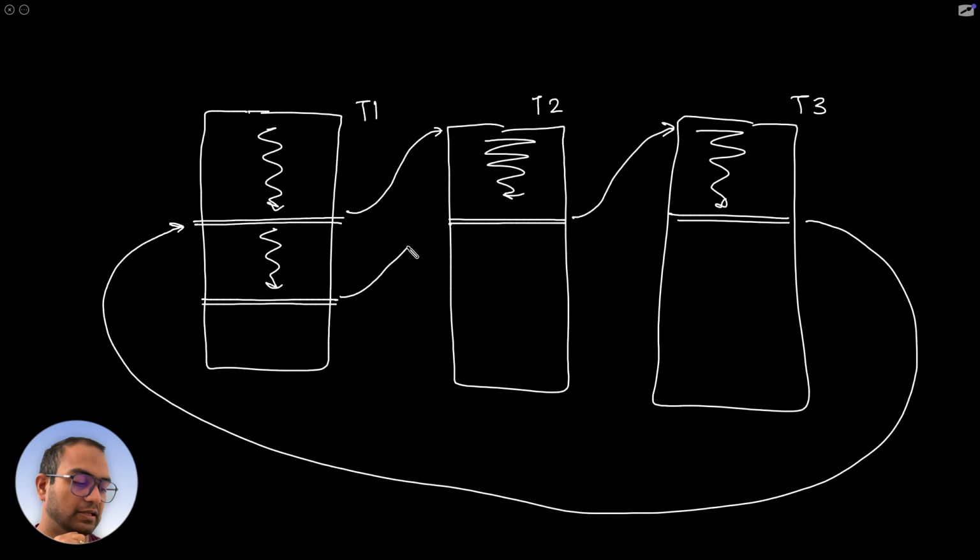So when it hits the point B, if we can somehow get the CPU to jump, or rather the program counter value be set to T3, the starting location of T3, then the instructions that correspond to T3 will be fetched. And exactly at the C point, if we could set the program counter back to the location A, or A plus 4, because A is where it paused, let's say, so the next instruction is what it wanted.